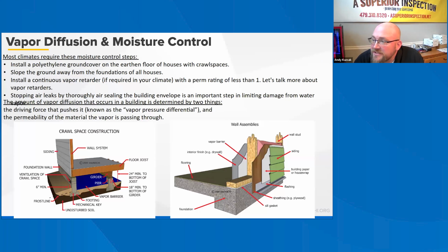In Minnesota, the vapor barrier is generally installed on the interior face of the wall studs. In warm climates during the cooling season, this vapor drive is from the outside of the building towards the inside. Thus, in Miami, Florida, vapor retarders are often applied on the outside of the buildings. Besides the perm rating of the material, the effectiveness of a vapor retarder is also a function of its surface area. A vapor diffusion retarder that covers 80% of a building is said to be 80% effective.